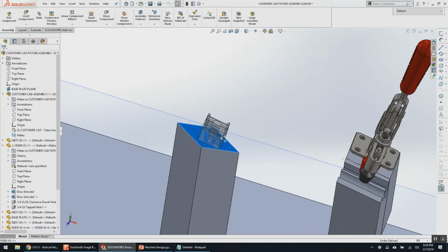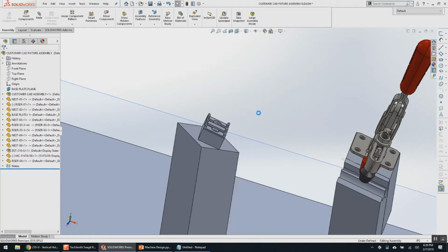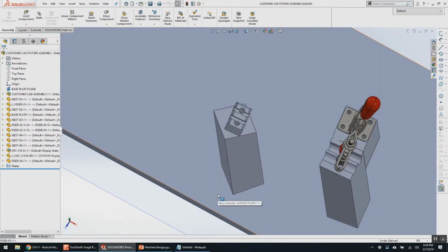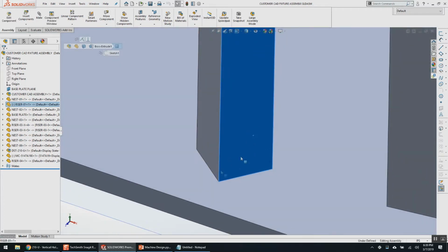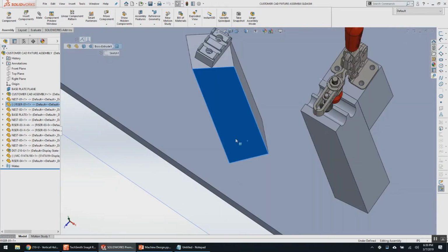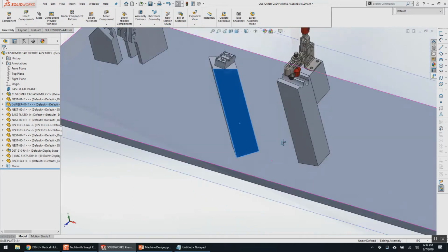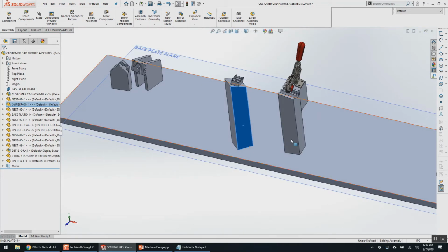Move it around. Sure. This seems like a very unspecific scientific method. It's because it is. In the world of external references and CNC design, I really don't care. I would put now a couple dowels in the bottom of this and a couple tapped holes, and then wherever this ends up, I would throw a mate or two on it and drive the holes of this block down into the base plate, which maybe I'll get to later today, or maybe the second session, maybe we'll get to some of this and start doing some detail work. We'll find out where that goes.